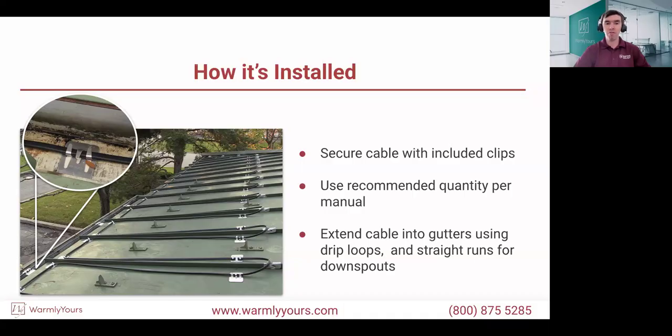So if there would be a foot of snow to the right or anywhere on this roof, we're not necessarily trying to melt all that snow. We're trying to create channels for the water to flow, which means if there are some chunks of snow still staying there, there still need to be roof guards or snow guard prevention methods in place.